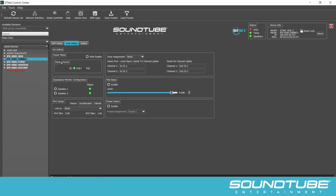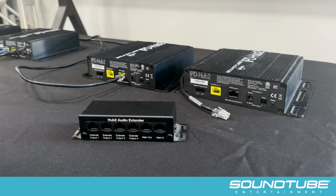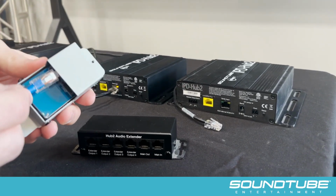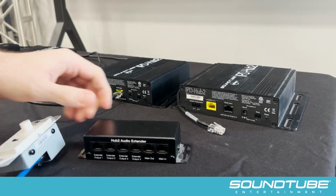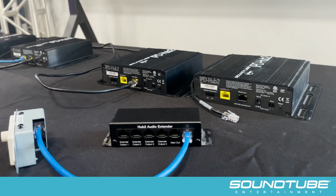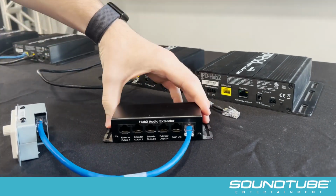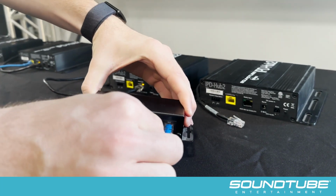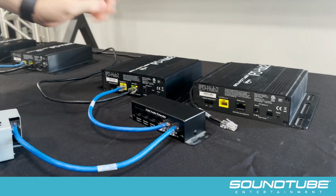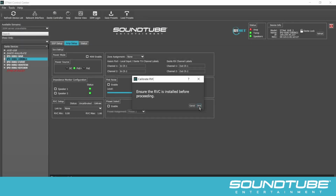Now in the Amp Setup tab, we're ready to calibrate our RVC. This one's a little different. We're going to be using the IPD-Hub 2 extender box to send our audio to both of the Hub 2s in this zone. We do that by connecting the RVC to the main in port on the extender box, and then connecting the main out port to the local input port on the primary IPD-Hub 2, which is our Dining 1 device. We then calibrate the RVC as normal.